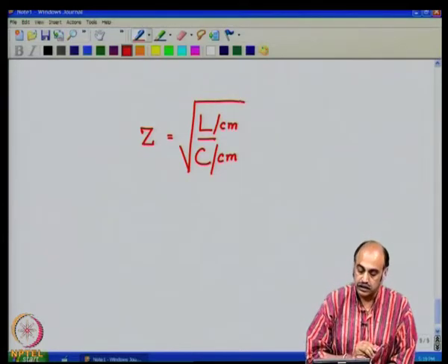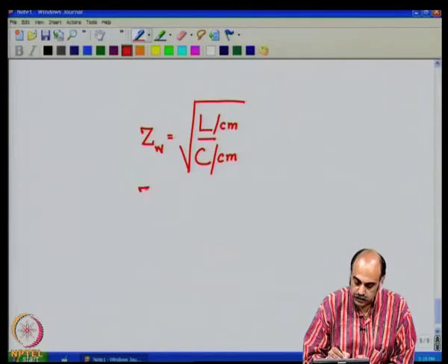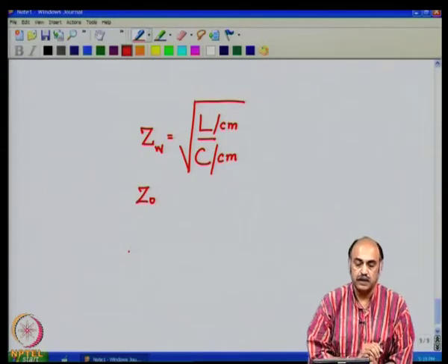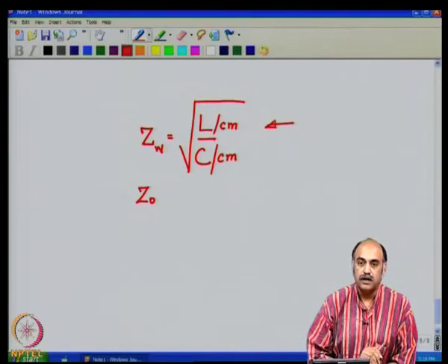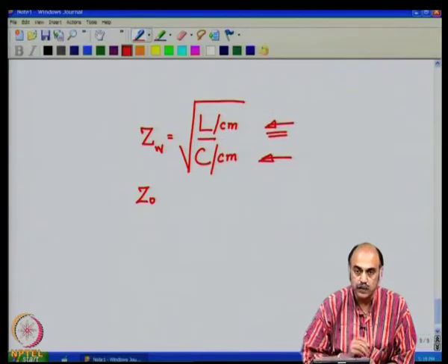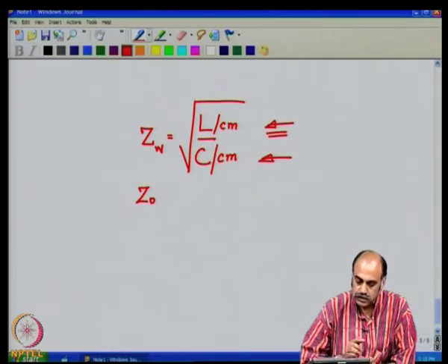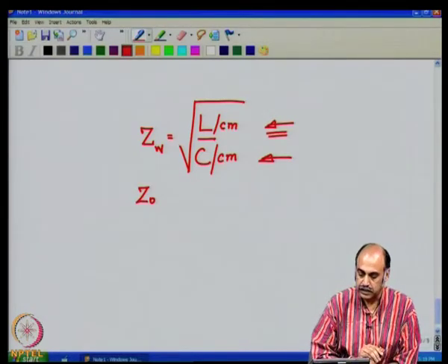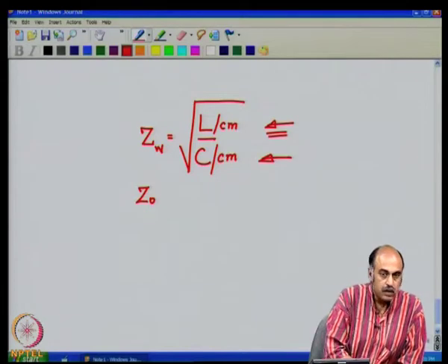This would approximately give you the wave impedance ZW or Z0 of that particular transmission line, and it is a characteristic of that transmission line because it is made up of the coupling capacity here and the per unit inductance value, which are basically characters of those two lines. So, this is the characteristic impedance of the transmission line, generally given in this form if the resistive part is negligible.